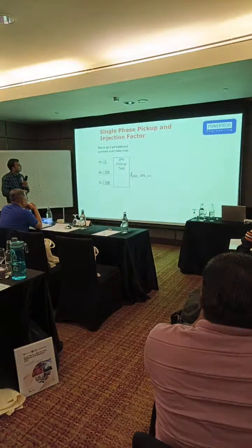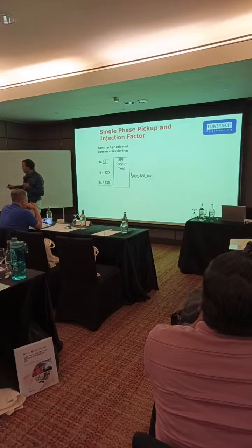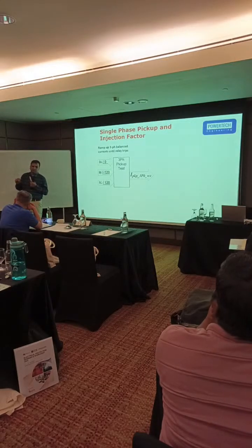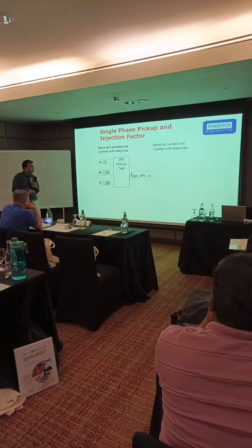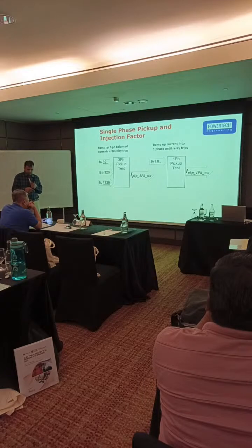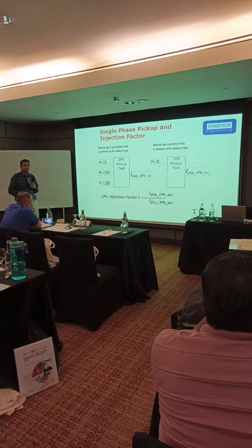First we take the three phase pickup. So we know what the actual setting and the actual pickup current are, and then we take the single phase injection and note down the pickup current in this case, and this single phase current is divided by the three phase current.